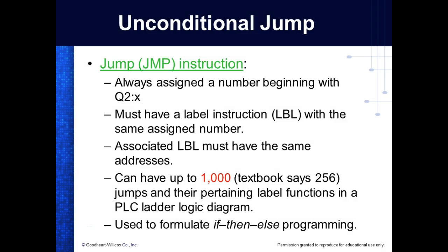Now we need to get through this. This is the new instruction we're going to pick up, called the jump instruction. Actually, it's an instruction pair. Some instructions you have to use in pairs. We have a jump instruction, and the jump will either jump forward or backwards in the program. It's looking for an instruction called what? Label. That makes sense.